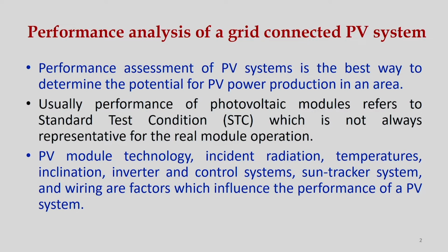Usually, performance of photovoltaic modules refers to standard test condition, which is not always representative of real module operation. The PV module technology, weather conditions like incident radiation and temperature, then inclination, inverter and control systems, sun tracker system and wiring are factors which influence the performance of a PV system.